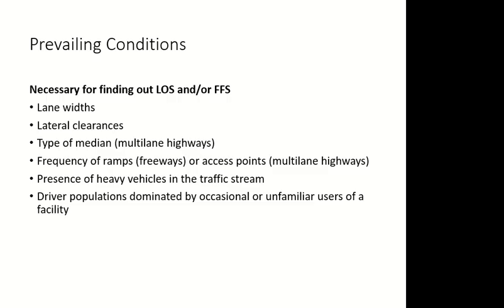I already explained to you the term TRD, total ramp density, so you need TRD for freeways. You need TRD for freeways if you are calculating the adjustment factor, and you also need it if you are calculating the free flow speed. It's the same TRD: go 3 miles forward and backward, count the ramps, divide by 6. It remains the same for both cases, but you only need it for freeways, because freeways don't have intersections, they only have ramps.